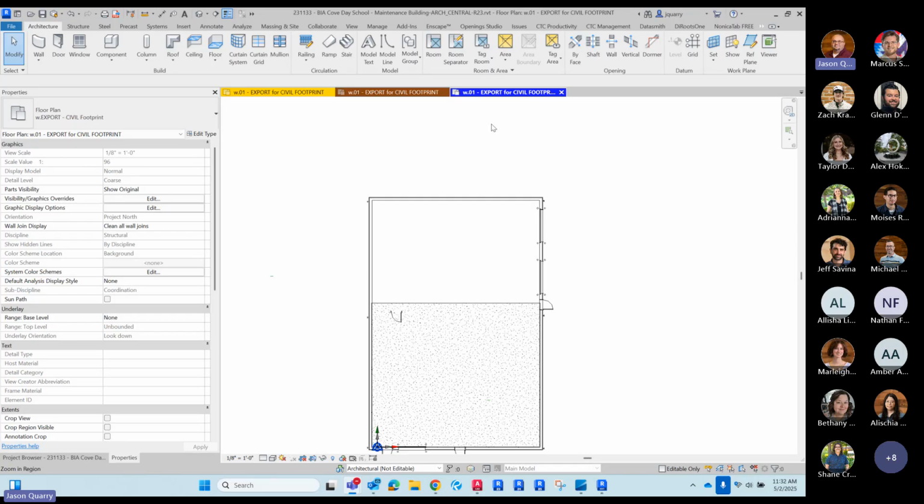There are some things that we've seen recently. I don't know how many of you have actually tried to link in a survey file or a file that you asked Justin Crane's team for, and you bring it in and it's all jagged. Or you get an error that says any lines that are far more than 10 square miles from the base point will have graphical issues.